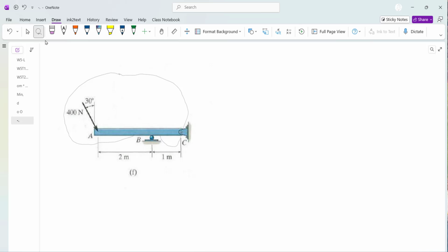So it not only includes the external force, also you have to expose the confining forces which used to be internal. Now you expose them as external. That is just to make this system equivalent to the free version. So this is the free version, A, C, and B. So external force remains as it is.